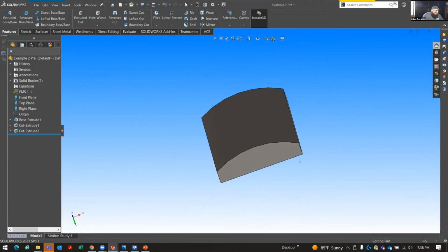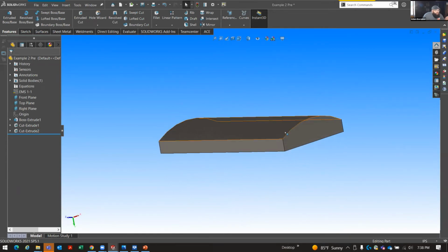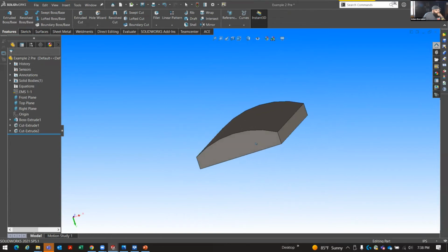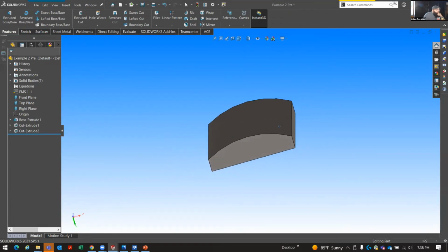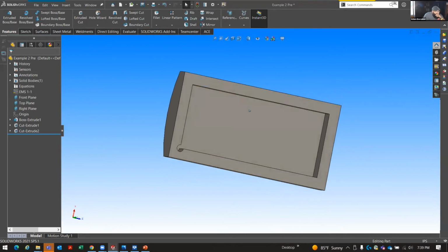This is all made out of aluminum. Any metal right now is not cheap. So it obviously has to be profiled on the bottom, right? But do I need these edges sharp all the way around? No. In fact, making those edges sharp is probably detrimental to the person who's assembling it. So putting fillets or chamfers in, fillets for us Southern people, fillets in.